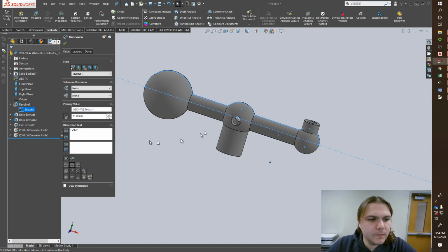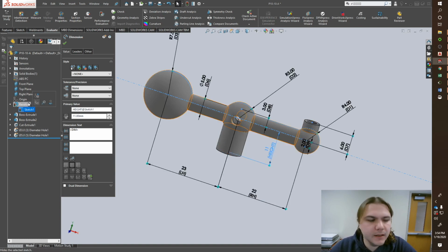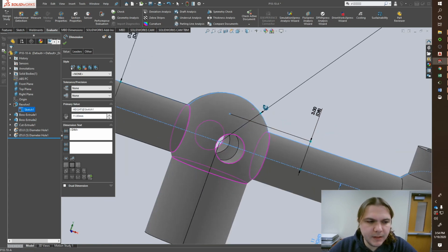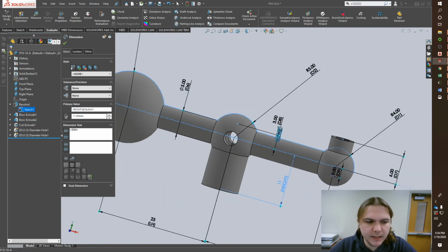Another couple things I did on my sketch: in terms of the overall height of this part, I have these holes that have a specified depth, and I don't want to have to go in and change those depths per whatever height setting I end up needing. So I put these points on my sketch and set a distance from my height to wherever they needed to stop.